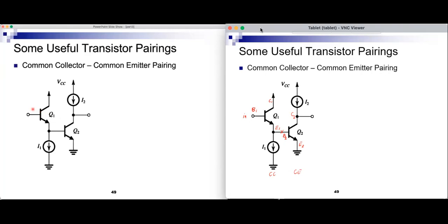What about other things like input resistance? What's the input resistance here? We will not show the small signal equivalent circuit, we'll just try to imagine it. The input resistance is the resistance looking into the base, so R pi plus whatever is between the emitter and ground. So what do we have between emitter and ground?